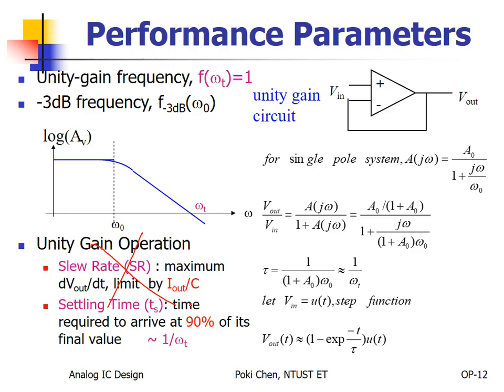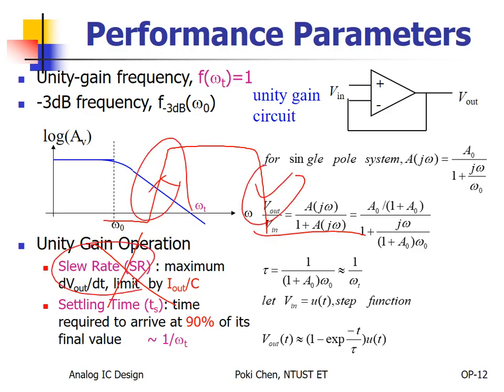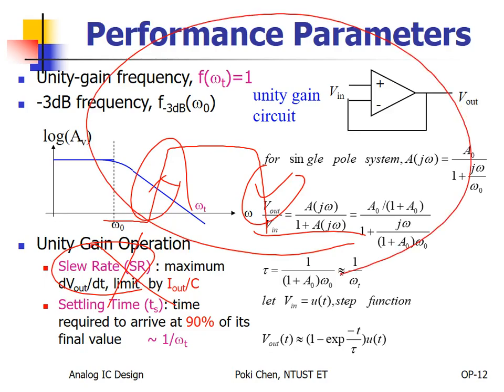Usually students and new engineers would like to make the output waveform as ideal as possible, so they would like to have a very good slew rate. Wrong decision. Too much chip area and too much power consumption usually means nonsense for your real design. Because the op-amp is only one of the many, many blocks in your analog chip, right? For each op-amp, if you would like to enhance the slew rate, you need to sacrifice a lot of area and power. It doesn't make any sense.